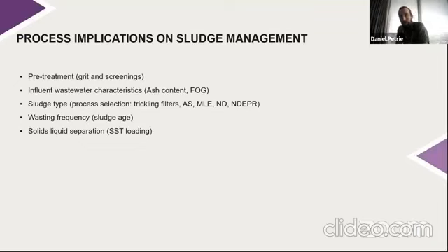And depending on the wastewater, how much of it is organic, how much of it is inorganic, how much of it is particulate, how much of it is biodegradable, that's all going to affect the quality of the sludge that you generate first in the primary treatment step, but also in the biological treatment step. If that wastewater has a lot of heavy greases from soaps or from restaurant waste, all of those things affect the quality of sludge that you're going to try and dewater.